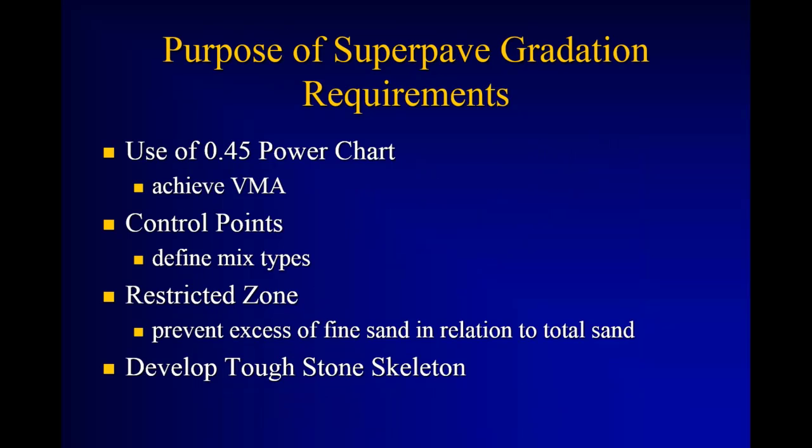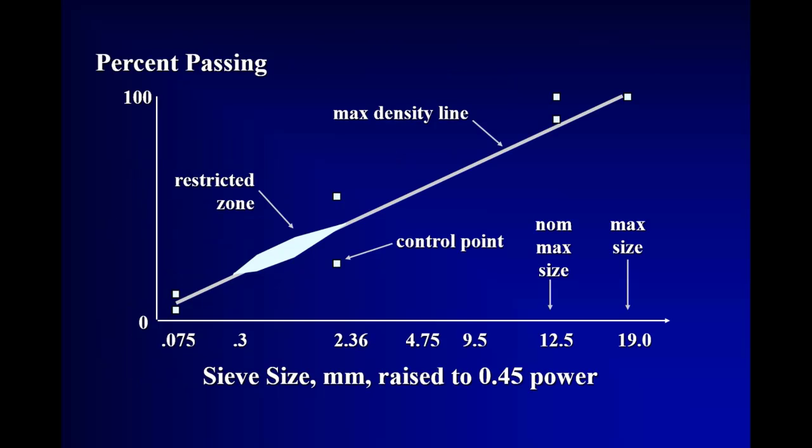In the use in asphalt mixes, whether it was Superpave, Marshall, Hveem, any of the standard mix design methods, VMA is extremely important. It's a common volumetric property. Voids in mineral aggregate, the intergranular void space in our compacted aggregate sample. So the distribution kind of gives us that VMA. We need to maintain that VMA.